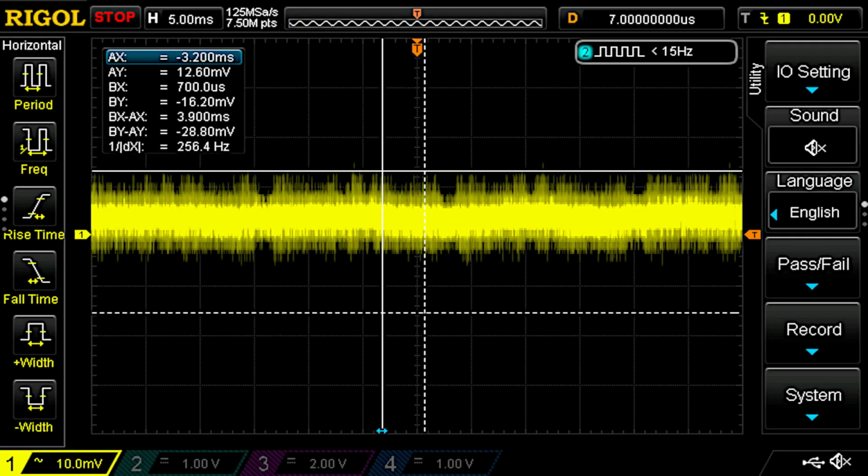Now the ADC input for the current sense looks very similar, but the waveform has a bit more noise amplitude than the voltage input. But this signal is from the current sense amp that is sensing the 1 milliohm current shunt, then goes through an op-amp with a gain of about 1.1, and then to an op-amp buffer. I'm quite sure the noise increase is coming from the current sense amplifier, but I will have to deal with that noise in a future episode.